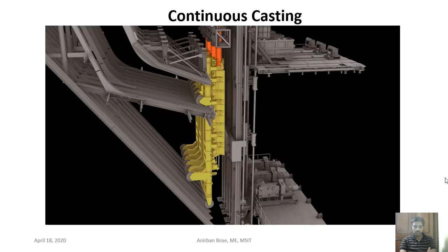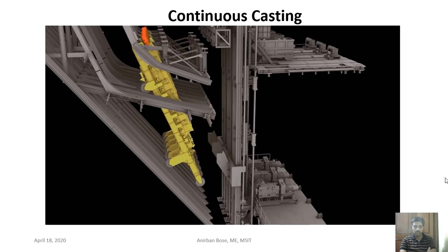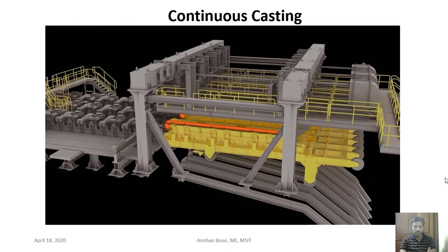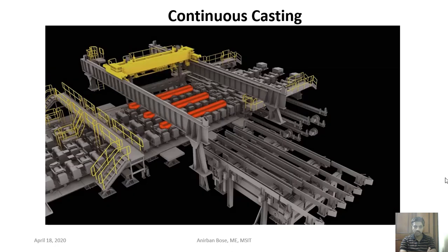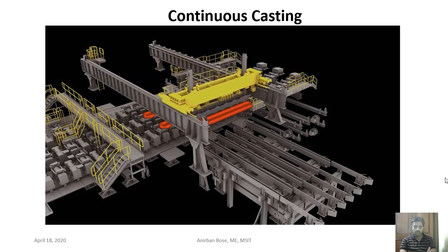After the bloom torch cut, a transportation car receives the bloom, raising it to ground level. A longitudinal pusher moves the bloom off the car and onto the discharge table. The blooms then travel to an aerial transfer, which picks up the product and moves it to the cooling bed.